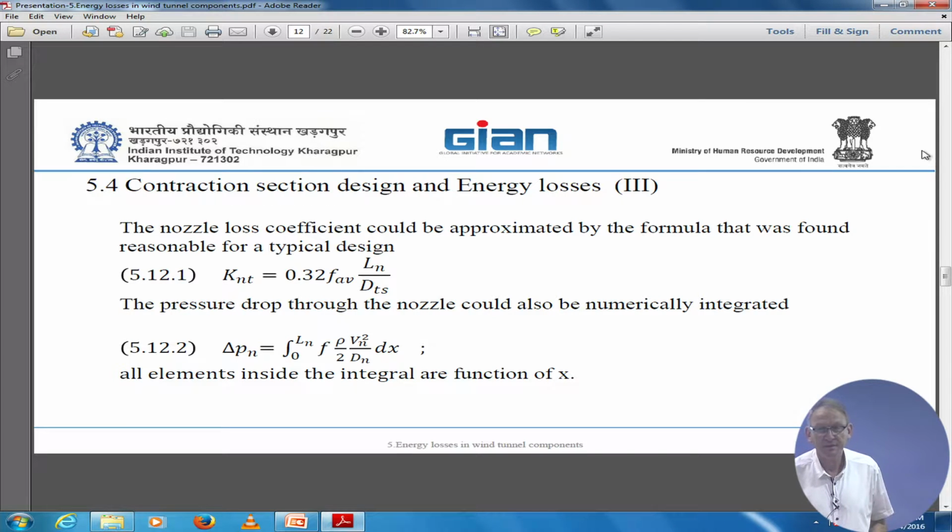There's a transverse motion also, instead of streamwise. That can stall the screen, so the performance is bad with the screen. So we want very straight flow before the screen. Screens will not kill eddies. They will only attenuate.